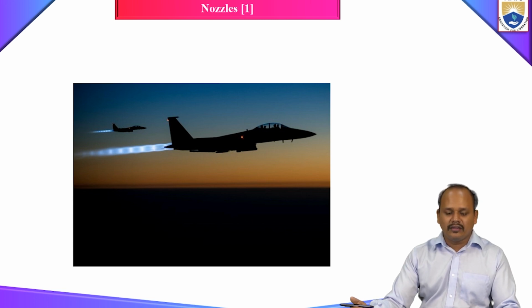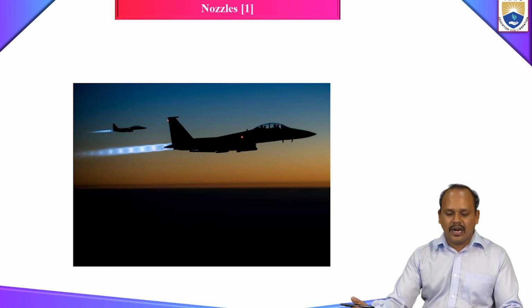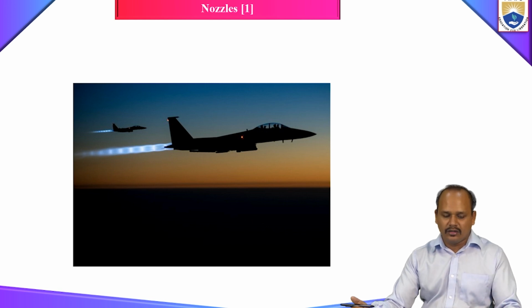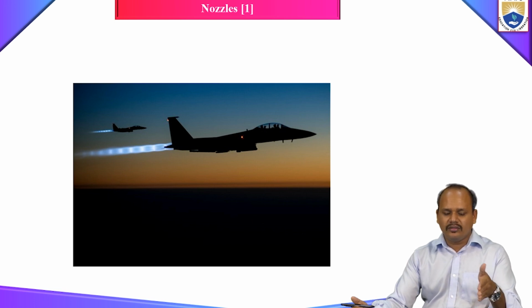One of the major noise sources in your fighter aircraft is the jet flow coming out. In the jet flow we have two noise sources. One is due to turbulence, another is due to shock wave generation. Why? First of all, the shock wave is generated because of the different operating conditions, either under-expanded or over-expanded. During the correctly expanded case, you won't have the shock cell formation.